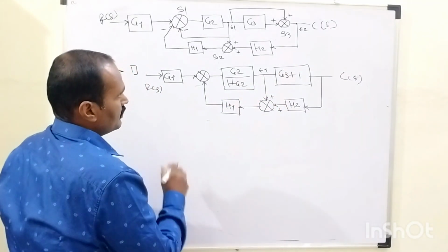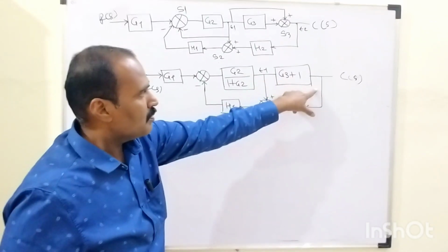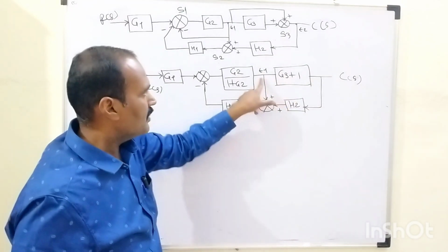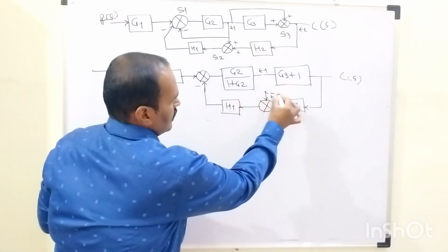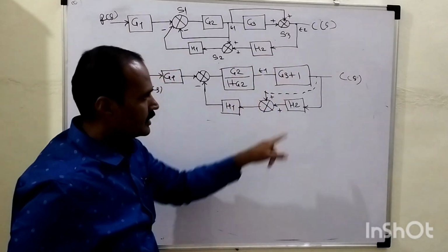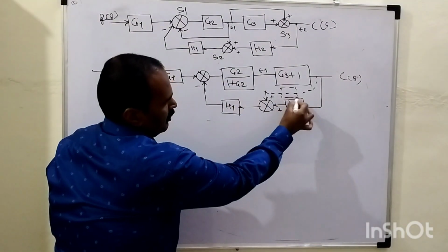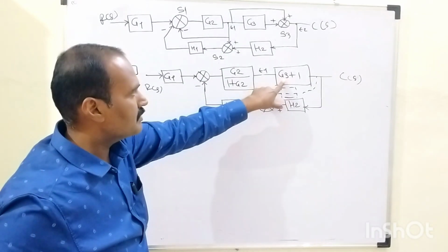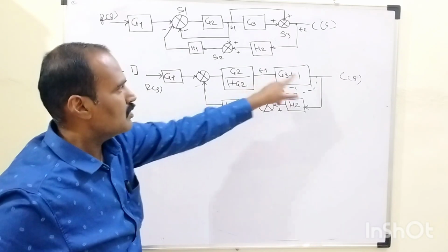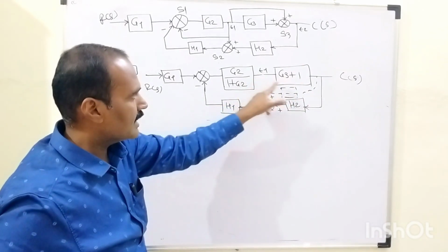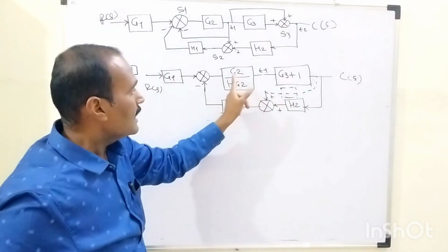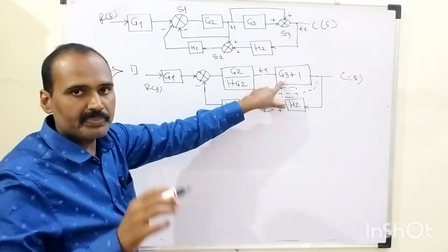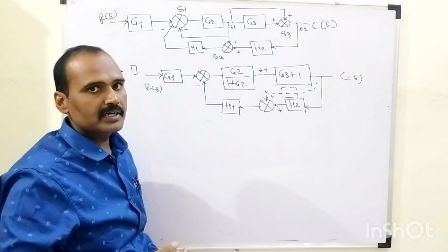As a result of doing this, once this takeoff point is shifted towards or after this block, like this, we need to add one more block whose gain is exactly equal to the reciprocal of the original one, 1 over G3 plus 1. But what will happen once that takeoff point is eliminated? These two blocks are connected in immediate series form, so their gains are multiplied with each other, right? So within the same step, we are going to perform two different things.